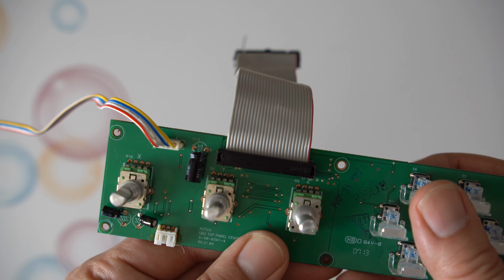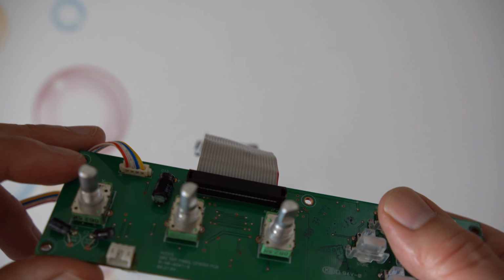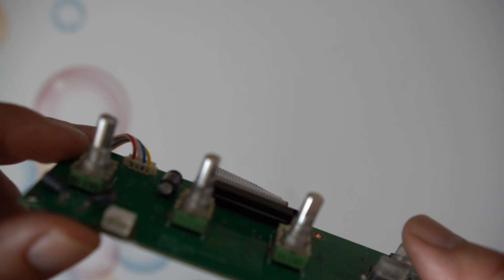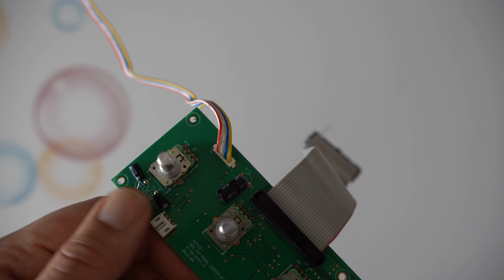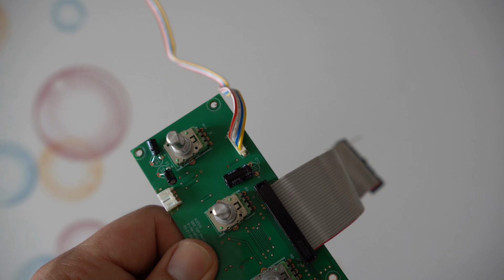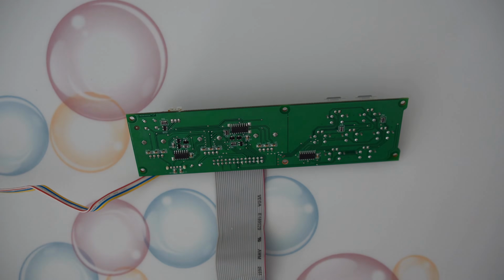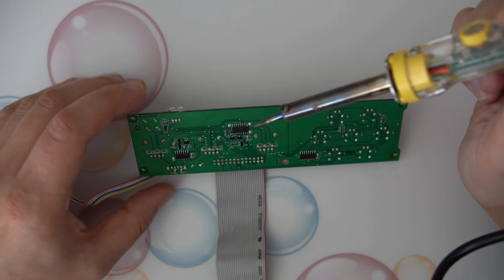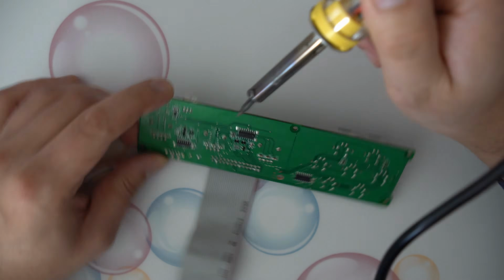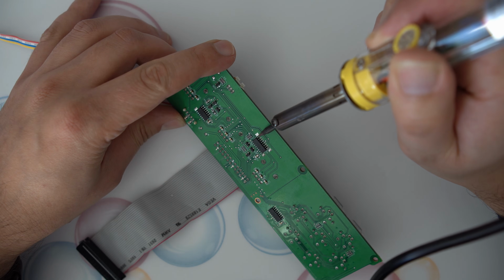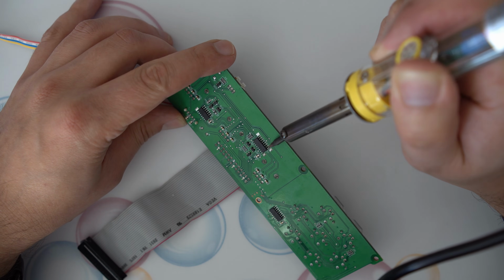These electronic parts often dry out or explode, leaking the chemicals onto the PCB. Faulty capacitors can easily be spotted by the bulging tops or by visible spillage on the PCB. These capacitors here look fine though, so I guess those aren't the culprits here too. The next thing to check is if there are broken solder spots, which act as resistors. These can normally be repaired by reheating them with a soldering iron, but in my case that didn't help the situation either.